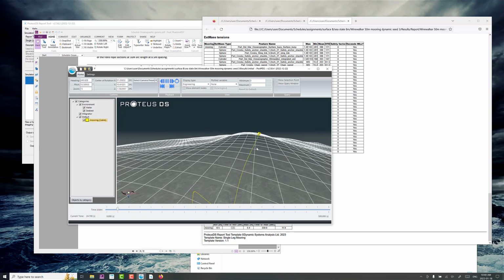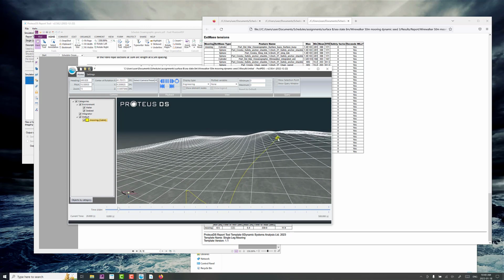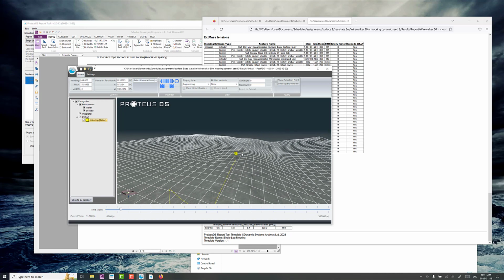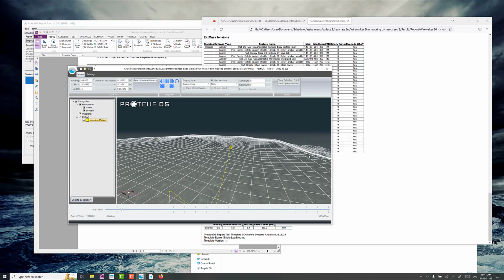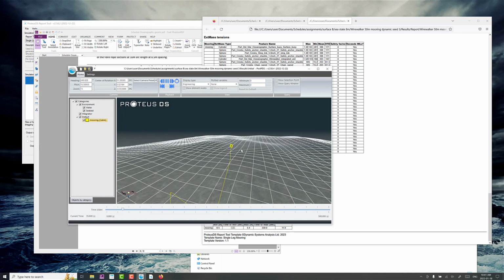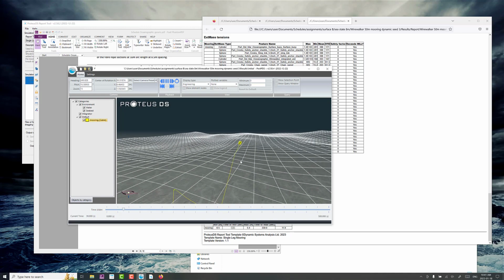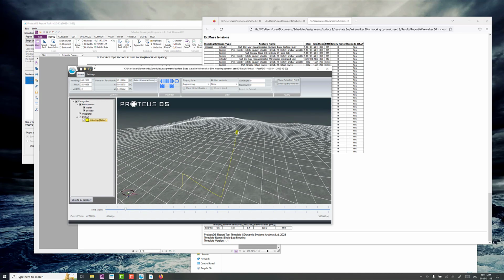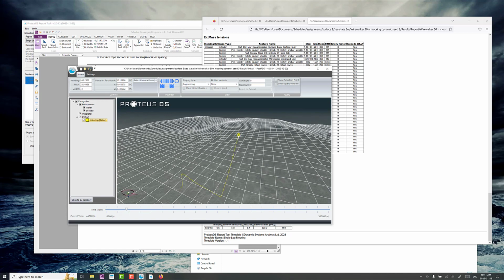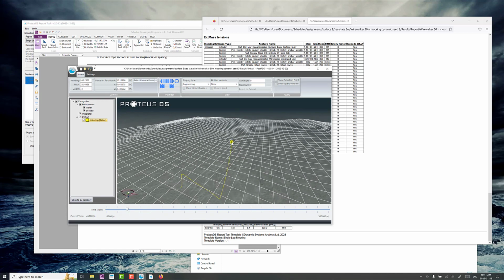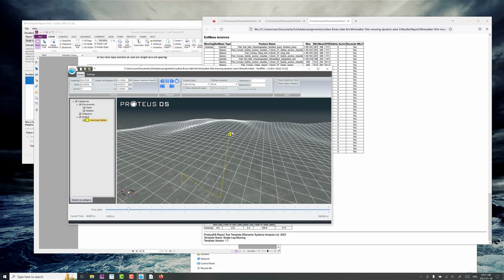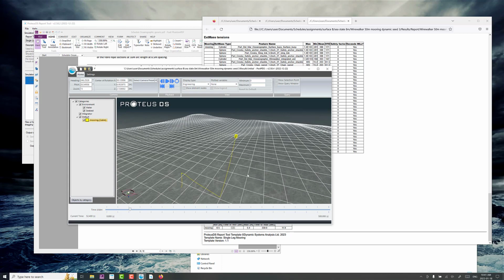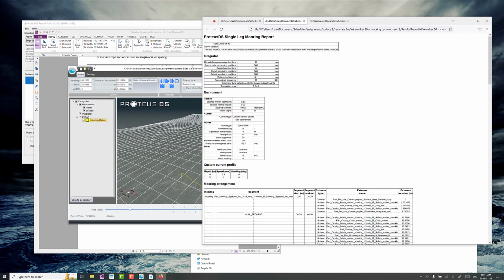So it looks like just at the crest here, the buoy's submerging a little bit. That could be realistic, and it's not a huge depth, but it's something, and you just probably want to make sure of that. I'm not sure there's much you can do about the mooring design with that, because it's doing a pretty good job generally. It's just that one big wave that came by. So you factor that into the planning and use of the surface buoy that you have, because there's a chance that it could happen there. So yeah, other than that, let's check the other reports really quickly.